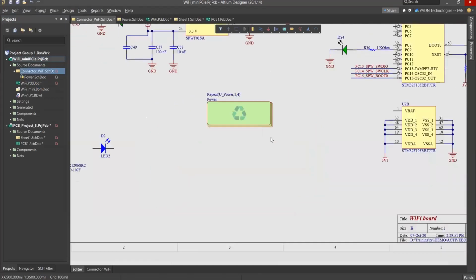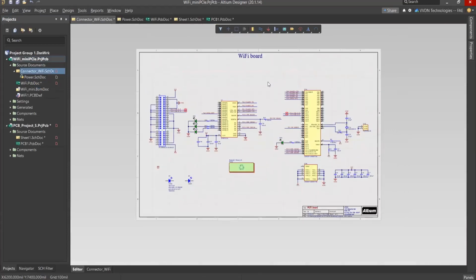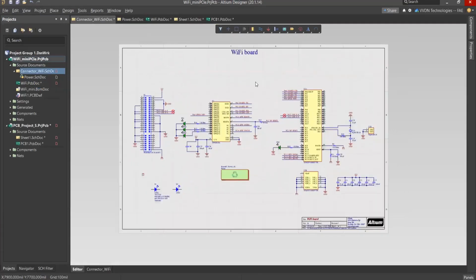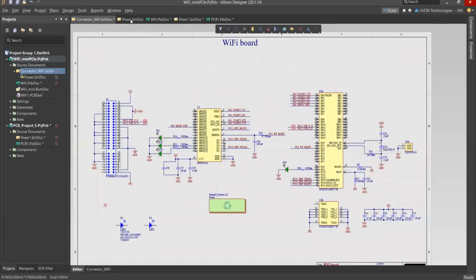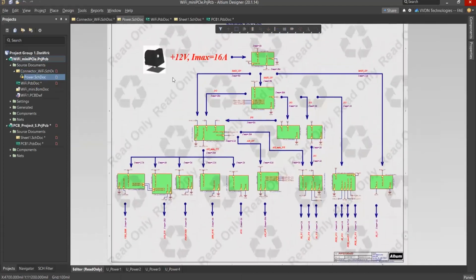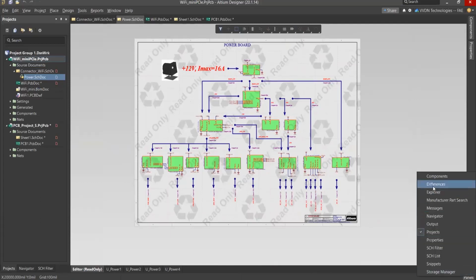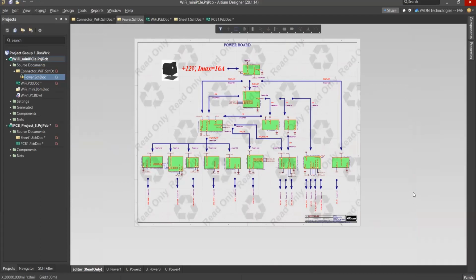Okay, so managed schematic sheet, instead of snippets and all, so this power supply, this one we want to reuse, right? So this one we can save as a managed schematic sheet, we can save under our Altium 365 workspace. Okay, so for that what you have to do, go to panels and we have the explore option.